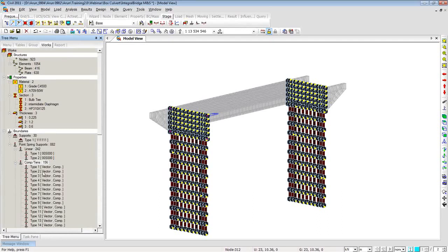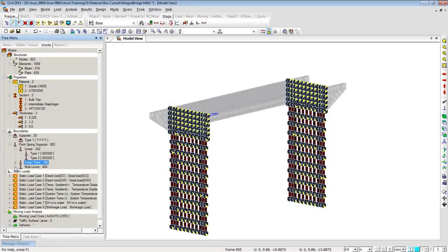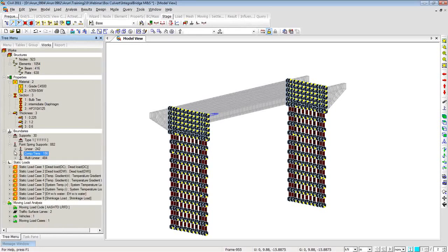Or you can go in and modify the values. Basically, let's say you see that for some reason at the base of the pile some spring conditions or soil conditions cannot be replicated in the program. So what you can do is enter those spring data from your own set of spring coefficients. So you can see how flexible the program is. It ranges from a completely program auto-generation feature to a completely user defined format. So you can take control in your hands, and you can go to whatever extent you want in this software.